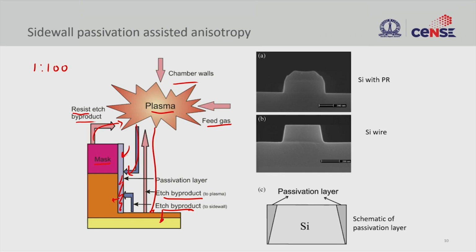So the AFM picture on the right side, right, this is silicon with photoresist. What you see here is the photoresist area, and what you see here is this strange coating. When you don't remove it, you can see the sidewalls are pretty good, 90 degree or so. But when you clean the material, the photoresist, and strip the material, you will see that it's not 90 anymore.